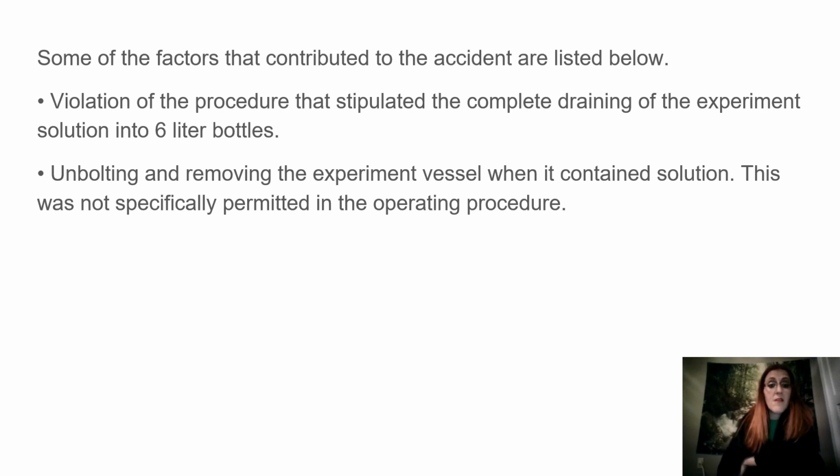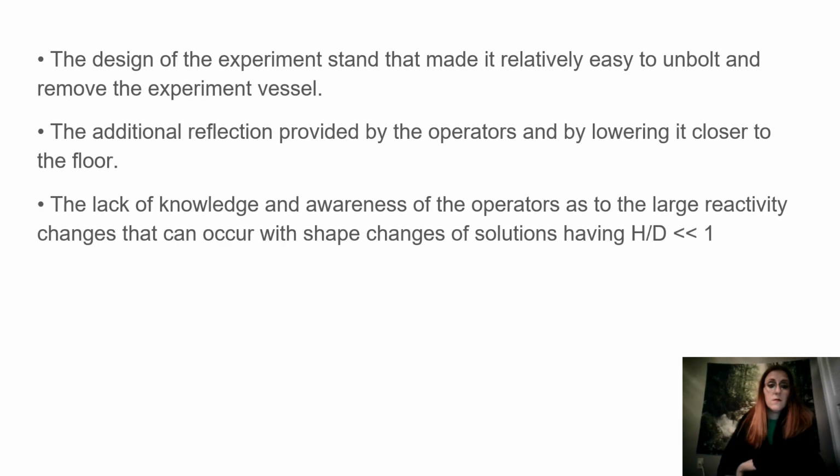Violation of the procedures that stipulated the complete draining of the experiment solution into 6-liter bottles. Unbolting and removing the experiment vessel when it contained solution. This was not specifically permitted in the operating procedure. The design of the experiment stand that made it relatively easy to unbolt and remove the experiment vessel. The additional reflection provided by the operators and by lowering it closer to the floor. The lack of knowledge and awareness of the operators as to the large reactivity changes that can occur with shape changes of solutions.